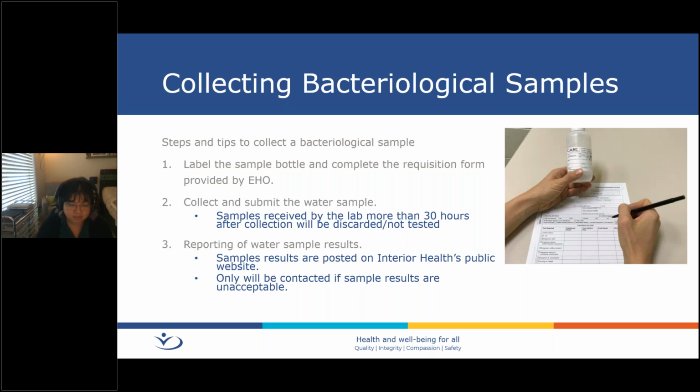And when you're submitting the water sample, ensure that it is submitted within the 30-hour time frame. So typically, after you collect the sample, it should be dropped off at the sample collection location as soon as possible, because it does take time to get transported to the lab. And sometimes if the samples are received more than 30 hours after collection, the sample may be discarded or not tested. And it's always important to confirm the drop-off hours with your local office. Sometimes if the samples are dropped off late, they may not be shipped out.